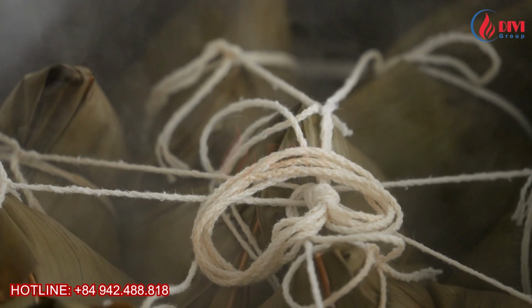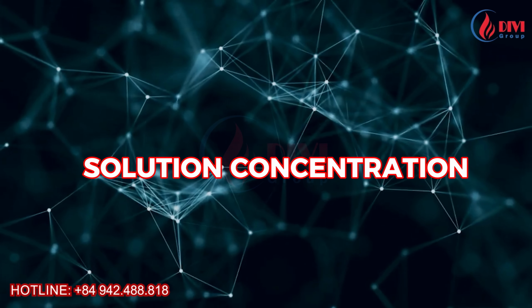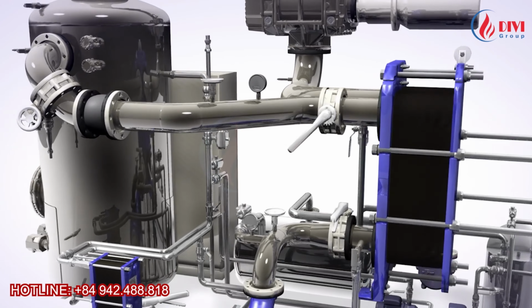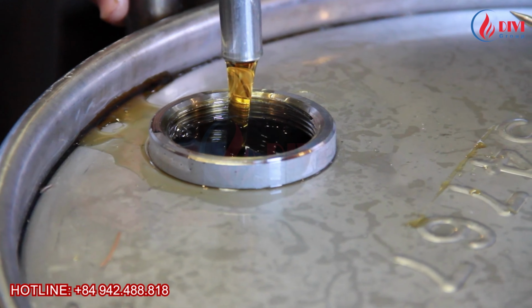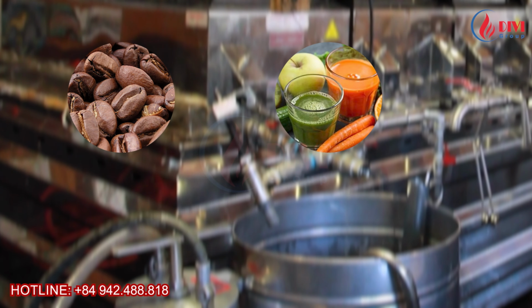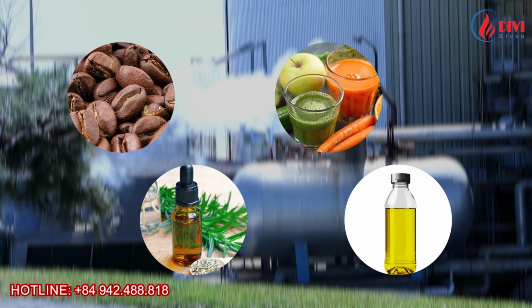These are the practical benefits that an industrial boiler can deliver. Application 4. Solution concentration. Building on the same heating principle, steam is also widely used for solution concentration. Concentration is the process of removing water from a solution to increase its concentration. Typical applications include concentrating sugarcane juice, coffee extract, fruit juice, herbal extracts, edible oils, and many other liquids used in the food and chemical industries.